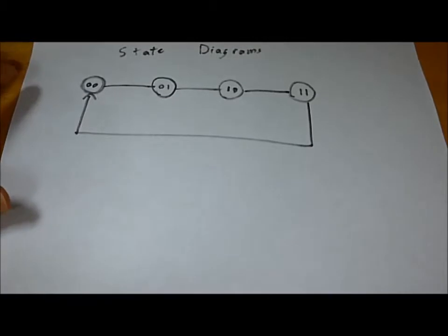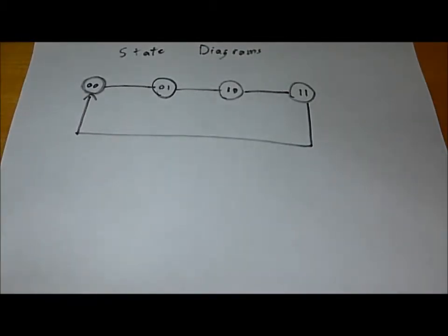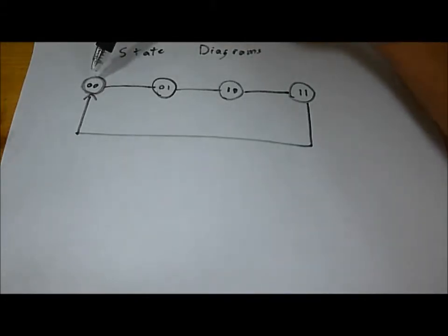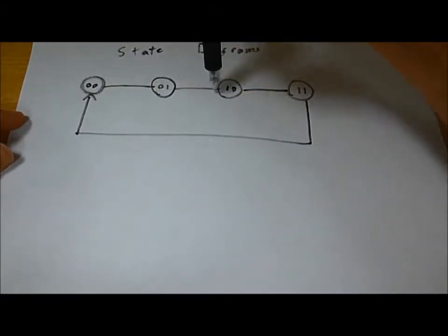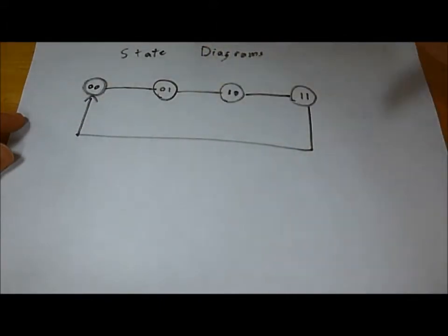So, how do we do this? Well, previously we looked at combinational logic and K-maps to cover how to determine the combinational logic equations for what our circuit was. For a sequential logic, we use state diagrams. State diagrams show us what state our current circuit is in. For an example, you can see we have 4 states here represented by circles. And we have an arrow going to each state.